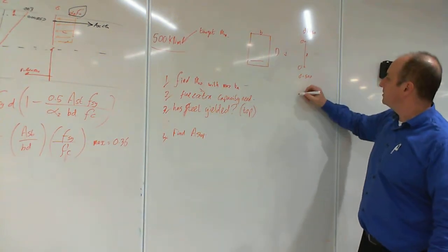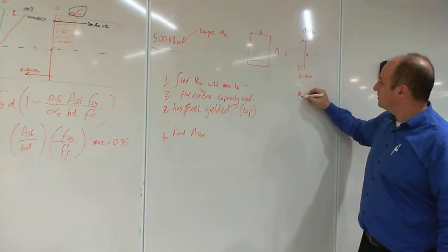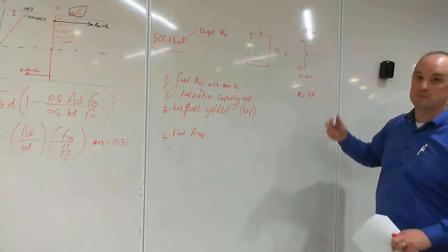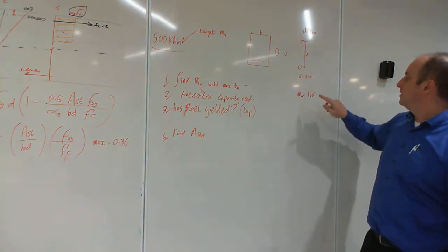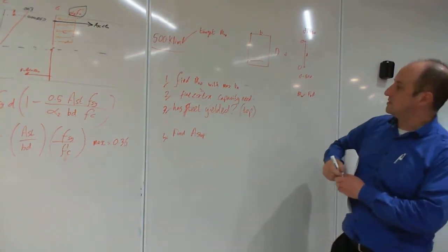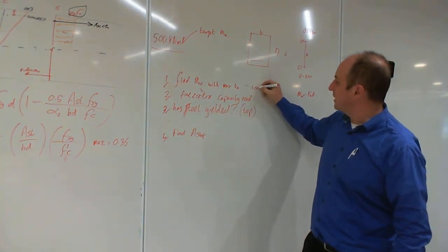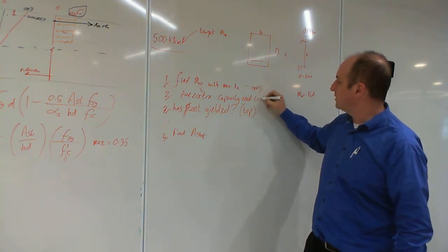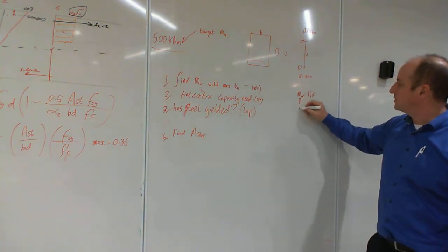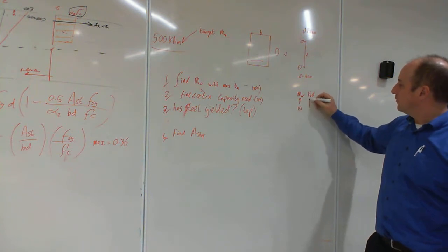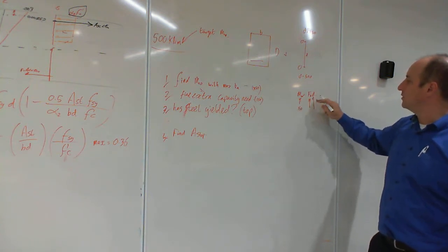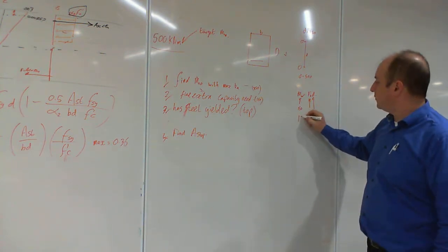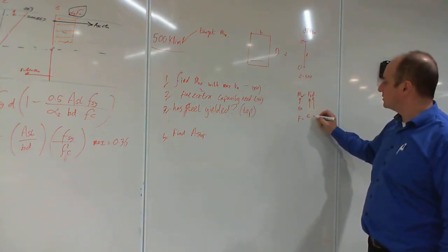And the moment for that is going to be the force in the steel times the lever arm. Easy. Let's say that was, for the sake of example, 350. Therefore, the extra capacity you need is 150. The force is what we're trying to find out. Now, once we've found out the force equals the stress.